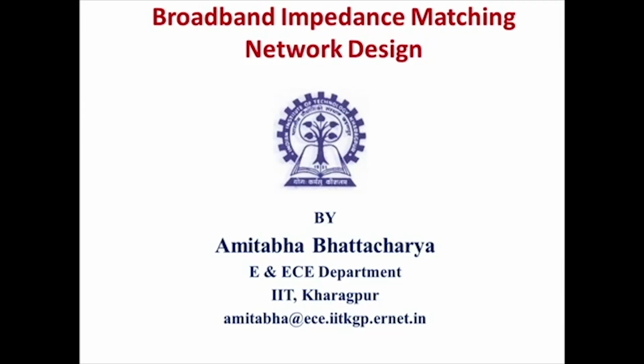This lecture will be on broadband impedance matching network design. As in the last lecture we have pointed out that single stub, double stub matching etc. are narrow band design schemes, but nowadays with the improvement of technology, wide bandwidth signals are coming. So, wide bandwidth systems are necessary. So, impedance matching networks in microwave frequencies need to also increase their bandwidth.